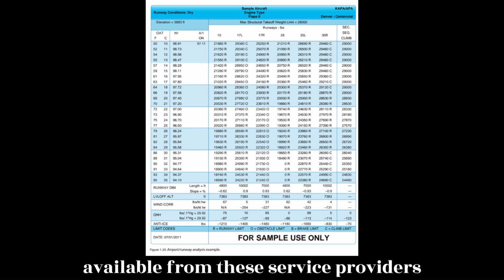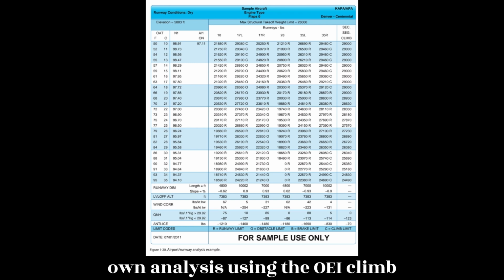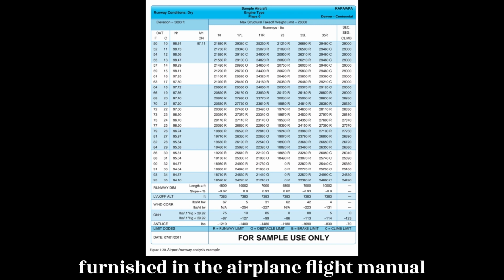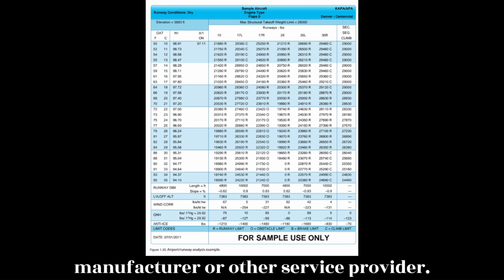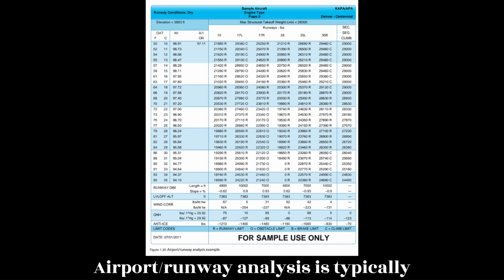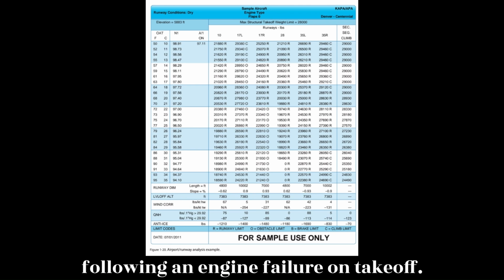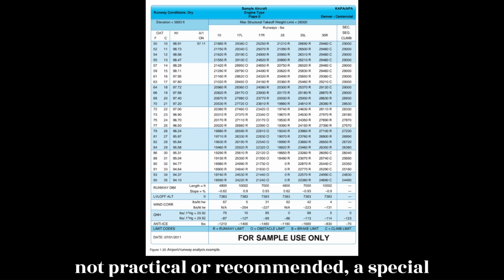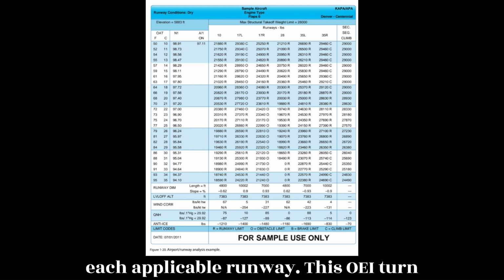Obstacle data also is available from these service providers for operators who desire to perform their own analysis using the OEI climb performance and flight path data furnished in the airplane flight manual or when using an aircraft electronic performance program supplied by the manufacturer or other service provider. Airport/runway analysis is typically based on the assumption that the pilot will fly a straight-out departure following an engine failure on takeoff. However, when a straight-out departure is not practical or recommended, a special OEI turn procedure can be developed for each applicable runway.